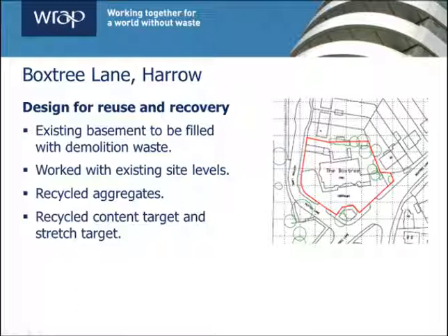Recycled aggregate was specified and used wherever possible throughout the site, and a minimum 15% recycled content was specified for the other building materials brought onto the site. In addition, an aspirational target of 30% was also included within the design team aims, and there was a particular focus on key materials to achieve this, including foundations, blocks, and windows.